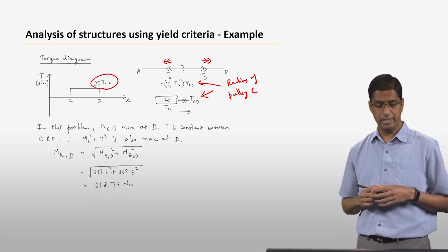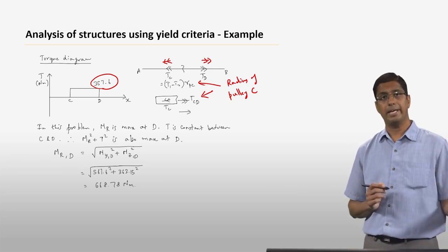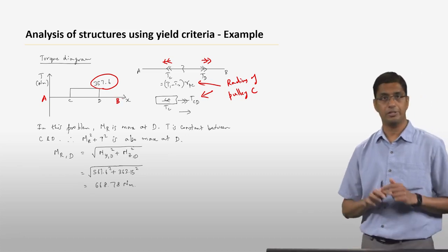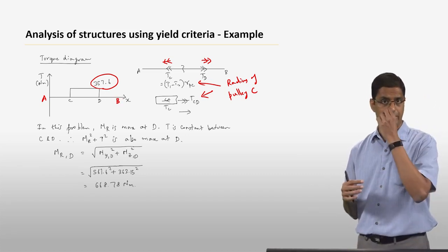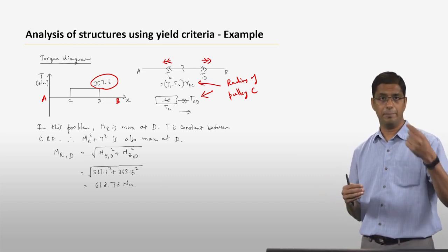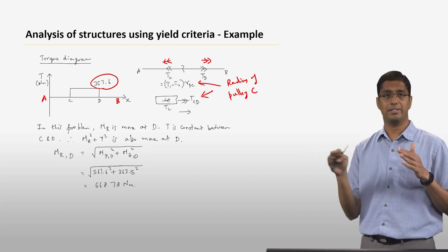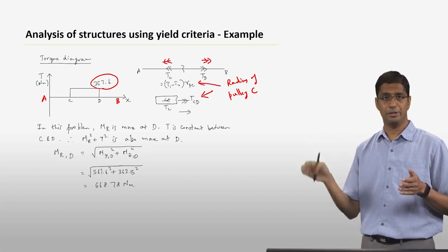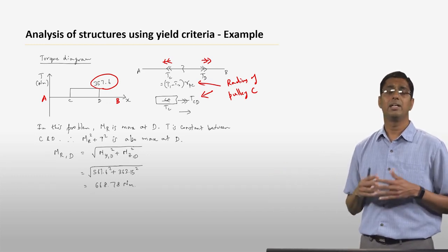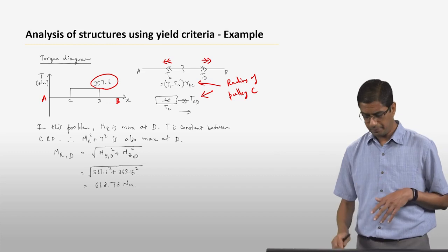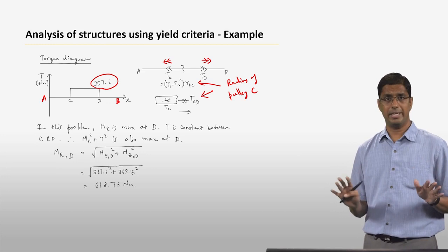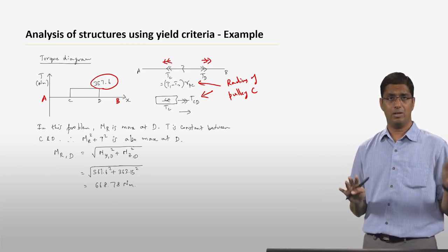So the torque diagram is going to look like this. Essentially, from point A to point C, it is going to be 0 because there is no internal torque in any cross section between A and C. At point C, you have a jump in the torque, and then the torque remains constant all the way from C to D, and then it goes back to 0. And again, from point D to point B on the shaft, the internal torque is 0. So essentially, now we have constructed the shear and moment diagrams, My and Mz, and also the torque diagram.